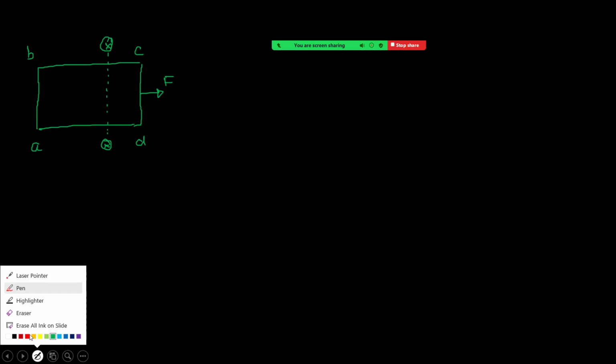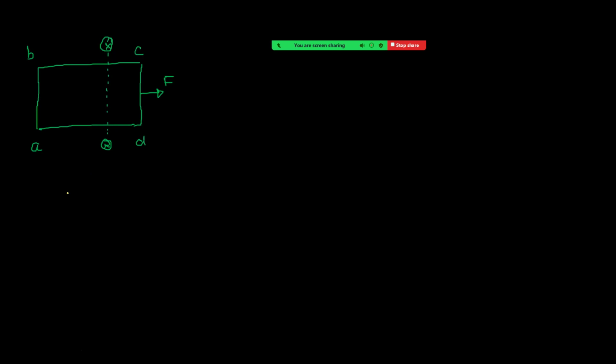Okay. So first of all, focus on how to calculate EMF induced. So again, take now Faraday's law, or directly we can use motional EMF. Okay. So we have motional EMF equal to L bar dot V bar cross B bar, right? You can see CD is not in the field. So across CD, there is no EMF induced.